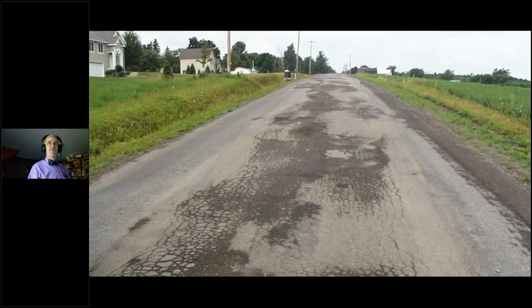And the one I would like to focus on is making sure we understand what the repair is actually going to do. This is not, I hope anybody would think, this is not a candidate for an overlay. And yet that's what this particular township was going to do, or town, for those here from New York. They were going to overlay this. And it's certainly not a good example of a place where you would want to do any kind of overlay. It really needs to have a rehabilitation or a reconstruction, a full depth reclamation, something like that. And of course, the only way you really know is to test it, see what's underneath, test the material, and find out.